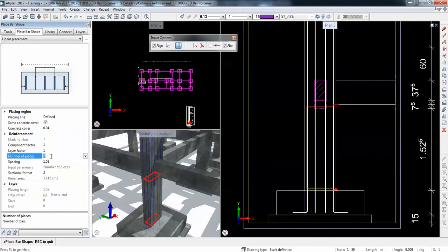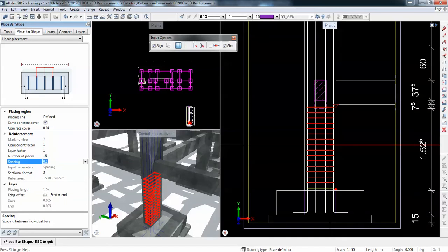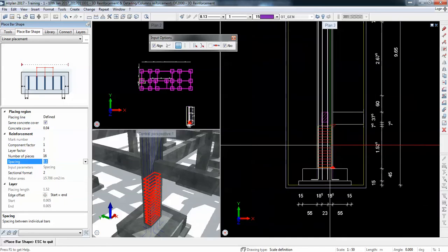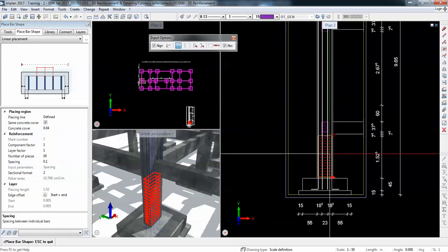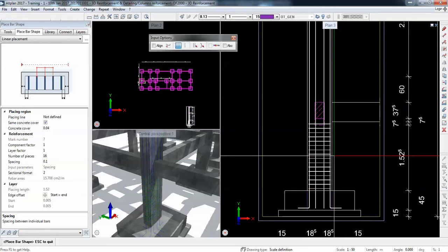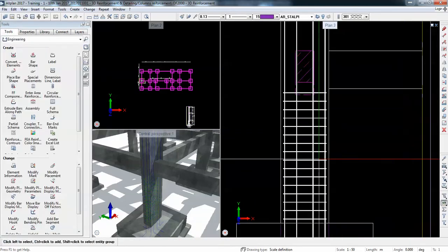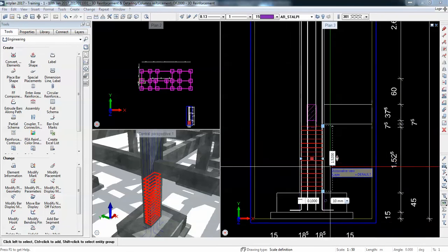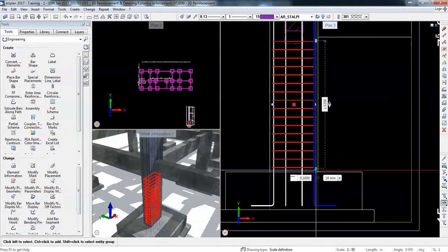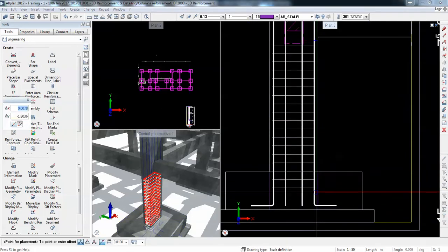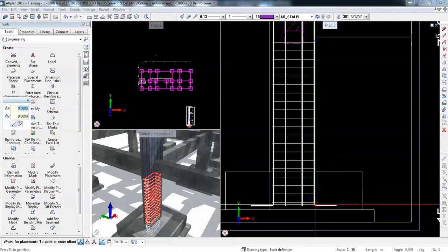And okay, the step is not okay. I can see 0.1. Okay, so start from the bottom of foundation. From the bottom, yes. Actually, I'll show you how I do the columns quite fast. So this stirrup placing, I usually take the minimum step of it, where we have the big shear force or plastic hinges possibility.